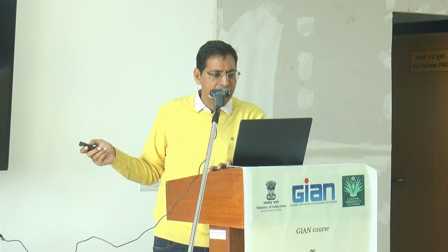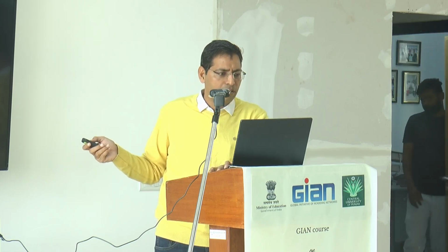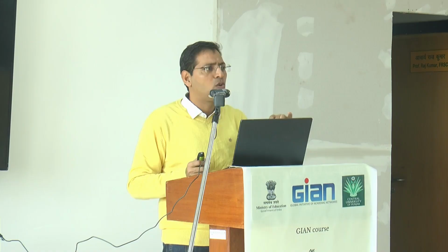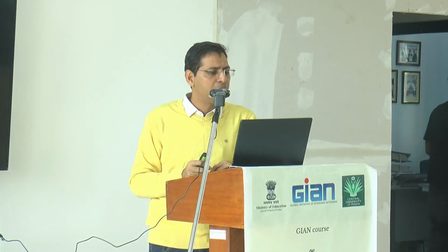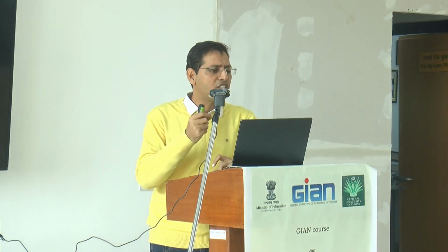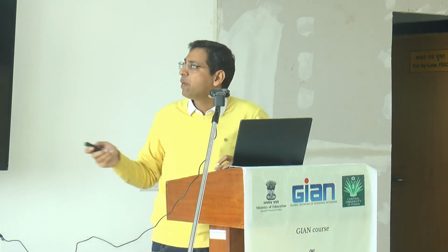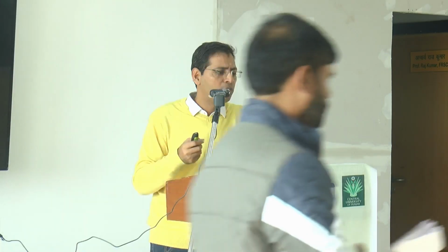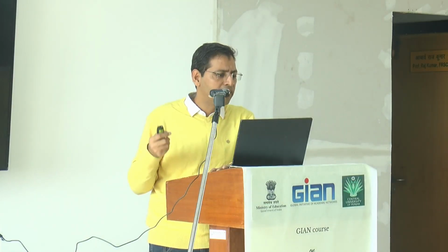So peak height is the height. Basically, in the ideal condition, peak height is just like a perpendicular length from the top down. You never find anything else. So this measurement can be done ordinarily. It is the distance from the baseline to the top of the signal peak. So you have to calculate the peak heights for HPLC quantitative analysis.